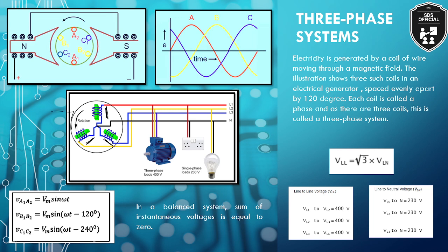Let us say there is a permanent magnet around these, north and south magnet. Now if these three windings are rotated, they will cut the flux of the permanent magnet. Now what will happen is, whenever a winding observes a changing flux with respect to that particular winding, as the rotor rotates, the winding will observe that the flux is changing with respect to time. It will generate a supply.